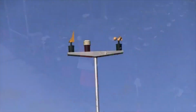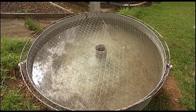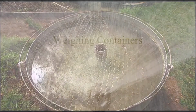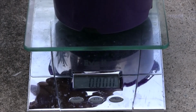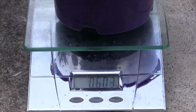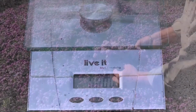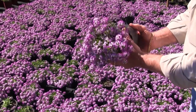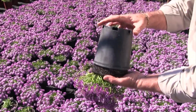Weighing containers and using data from an automatic weather station or using a Class A evaporation pan can assist with irrigation scheduling. Weighing a representative container from an irrigation block before and after irrigation can be used in conjunction with the irrigation manager's skill and experience to schedule irrigation according to the current weather conditions.